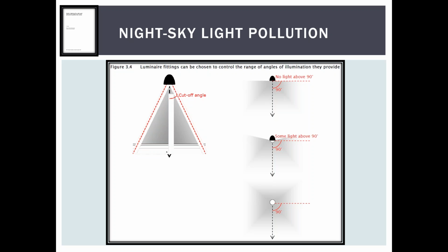For instance, some areas lit for pedestrians are also used by buses or delivery trucks. While a low luminaire mounting height may provide good lighting for pedestrians' needs, it could create glare for drivers of higher profile vehicles. Bright sources of light can be replaced with a larger number of weaker sources to reduce glare levels but still provide the same overall level of illumination. Interaction with glossy surfaces creating reflected glare should be avoided.